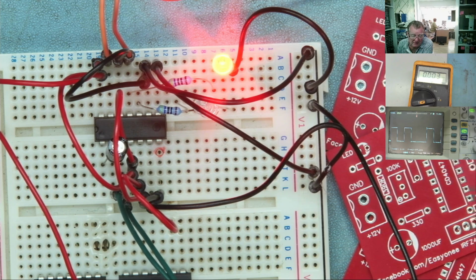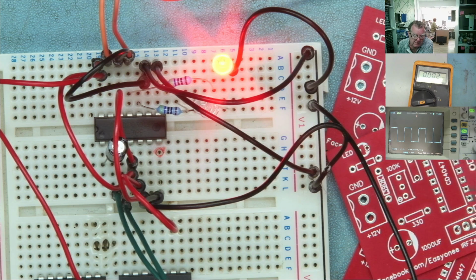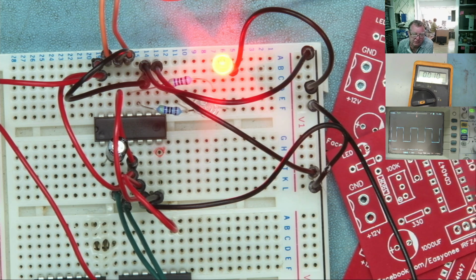And we see in fact that this is oscillating at the same frequency as the output, same amplitude and in the same polarity, so the electrolytic is just fine in there, doesn't cause a problem. But because the oscillator was running, really we knew this anyway, I just thought it would be good to prove this, so there you have the proof.